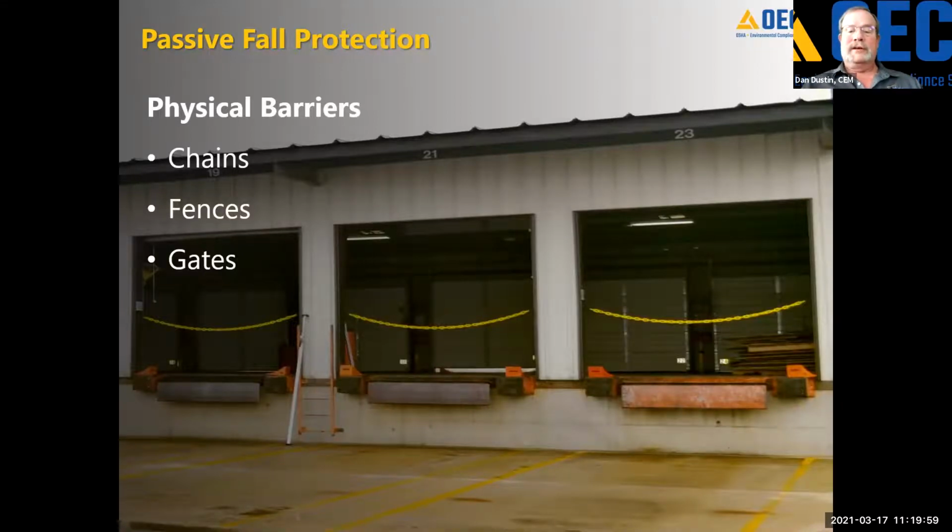But I have seen hard systems such as fences or scissor gates that they can put across these, or in some cases there are actually pull down additional doors such as screens that they can pull down over these that prevent you from walking off the edge as well. If they have to actually stop a forklift from going off, they put what they call a belly band in there that looks like a 6-inch wide nylon band that's securely anchored to the doorposts on both sides and would prevent you from inadvertently backing off the edge with a forklift.